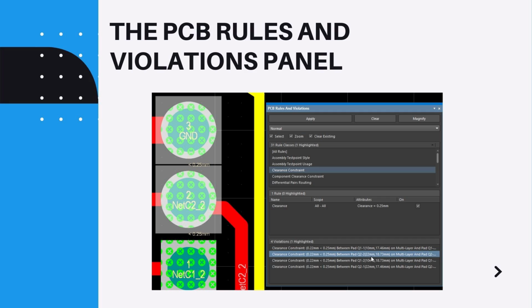The PCB Rules and Violations panel. The PCB Rules and Violations panel is an excellent feature for locating and understanding error conditions. Click on the Panels button, then select PCB Rules and Violations from the menu to display the panel. It will default to show all rules in the rule classes list.